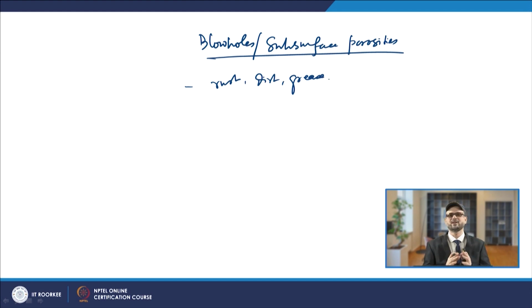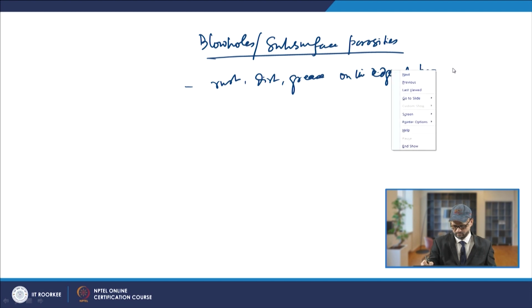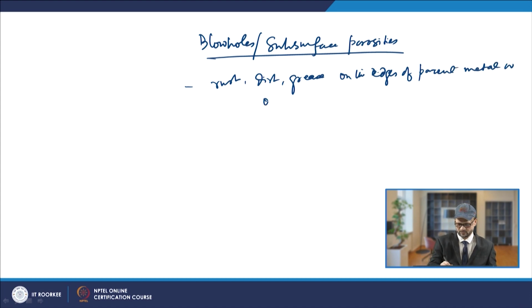If you are not able to clean them on the edges of the parent metal or on the electrode, this may be the reason for the blowholes or subsurface porosity.